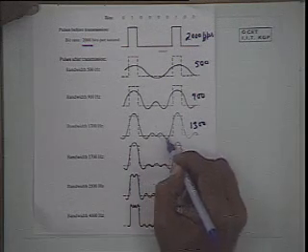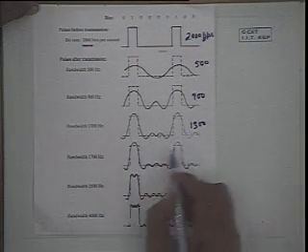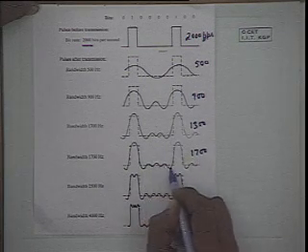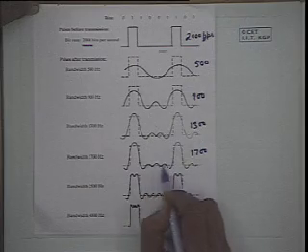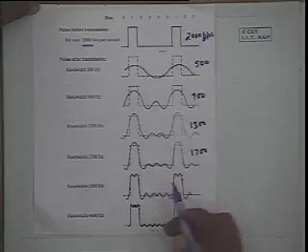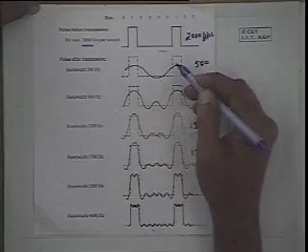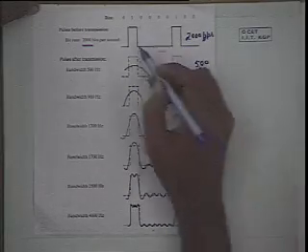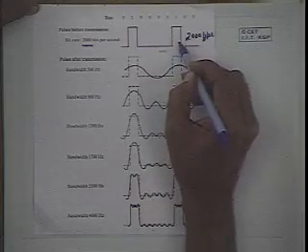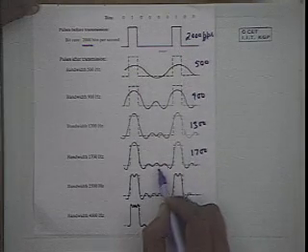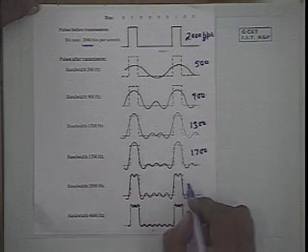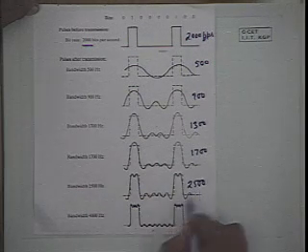More harmonics are passing, as you can see. If it is having a bandwidth of 1700 Hz, then more and more harmonics are coming, and it is becoming thinner. Here it is wider. That means we may not be able to detect this signal as converted back into this, but maybe this one or this one we may be able to reconstruct. And this is the bandwidth in case of 2500.